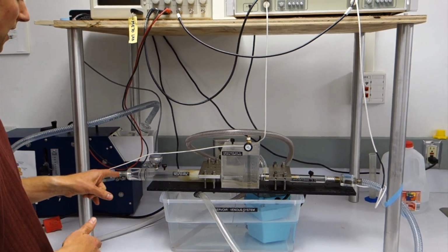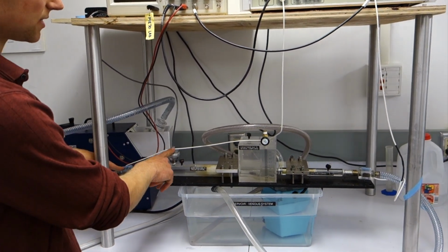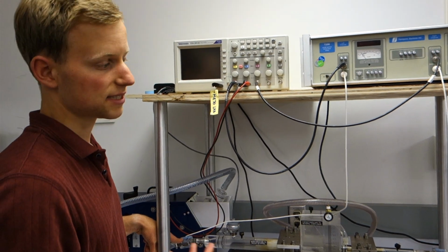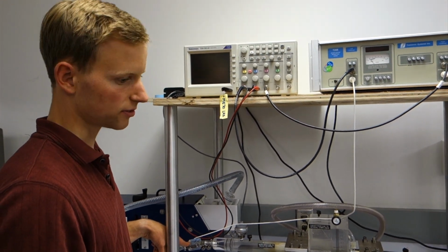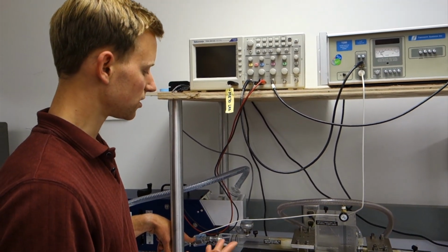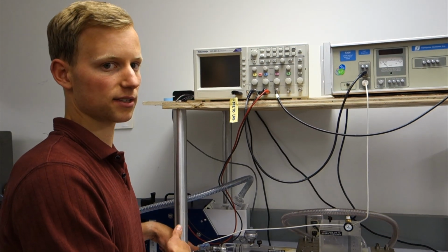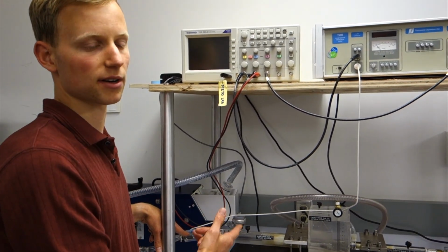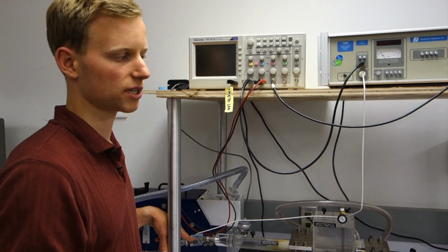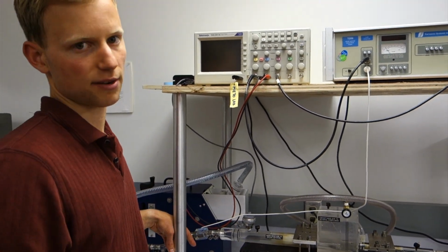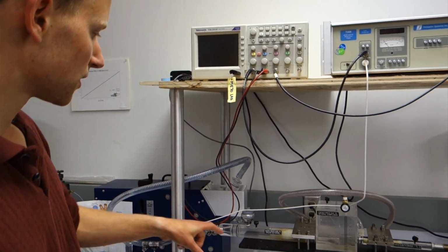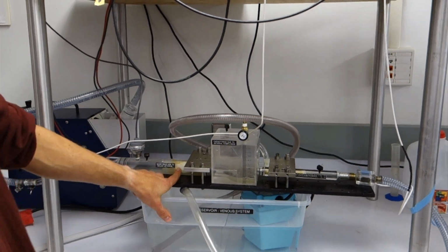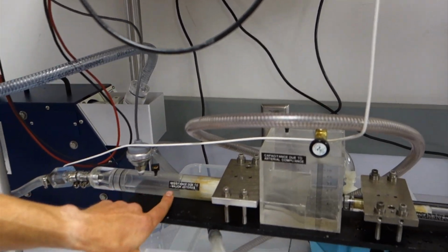But keep that in mind, that the values coming off of these sensors will be in volts, as any sensor does, maybe volts or current. And we want to know what the physical quantity is, Q and P. So we need to have a calibration or a transfer function that relates voltage and pressure, and then voltage and flow rate.